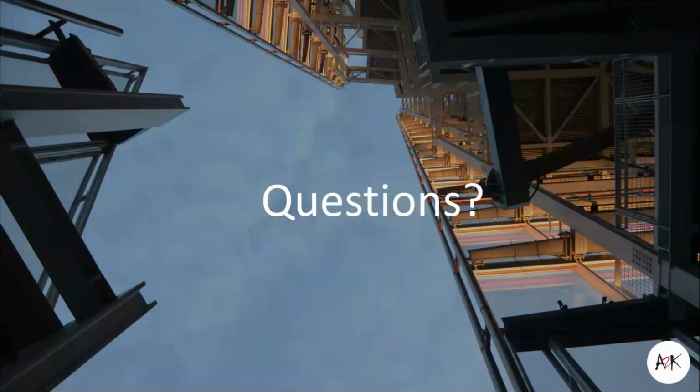Andrew's asked a question about translating into Revit. Thanks for that question, Andrew. At this point, I know there are some things in the pipeline for working more astutely with Revit. You might be familiar with the BIM translation from Inventor. Certainly we could model something in Fusion, take it into Inventor, and then convert it to an RFA file within Inventor, but not from Fusion as far as I'm aware at this point.